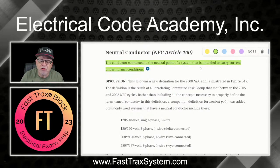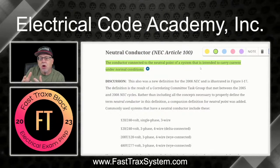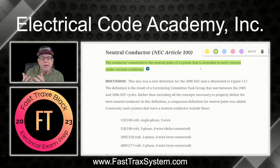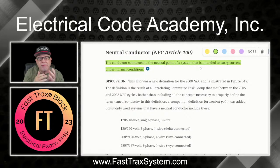And it's why it's so important for us to talk about improper neutral-to-ground connections downstream, where you connect the equipment ground to the neutral conductor improperly, because what you're doing is imposing current onto the metal parts, which are connected to the equipment ground. The equipment ground is serving dual roles, right? It's not only giving you a reference to Earth, but it's also being used as a bonding component.